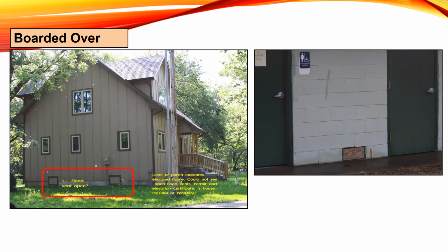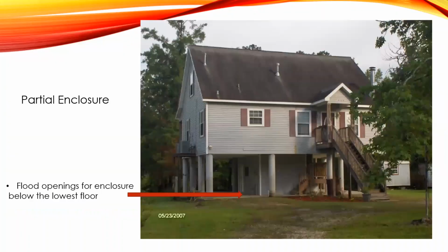Or if you have a retrofit project where they have to put in flood openings or additional openings, engineered openings might be a good option because they're rated for so much net opening, and that might decrease the number of openings that have to be installed into an enclosure. You can find engineered openings just looking online. Like I said, they're a little bit more expensive, but they could help someone in that case.